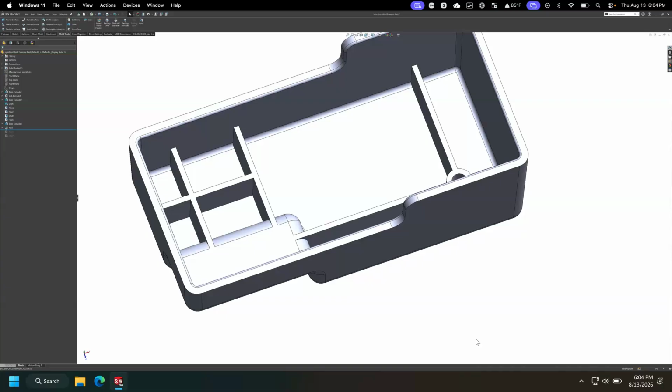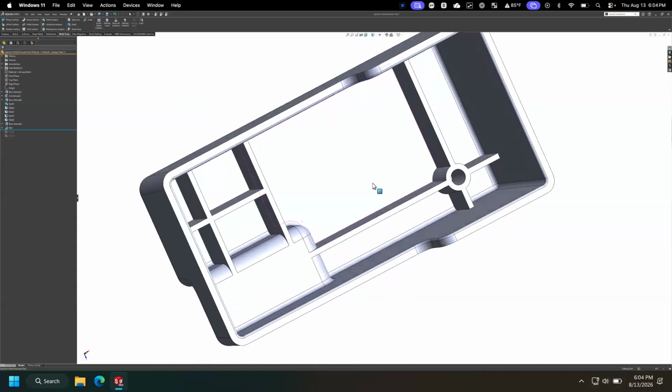Yes, that is something you often do want to consider. I will play the dumb designer who doesn't know, but tried to follow all the rules. Absolutely, number of ports, especially if there is an area like on a lens, if you're trying to have a clear feature or optic area, flow can definitely be a major concern there. You would want to call it out on your drawing that ejector pins and injection points can't be in certain areas, so that they avoid the area you're trying to keep clean, basically.